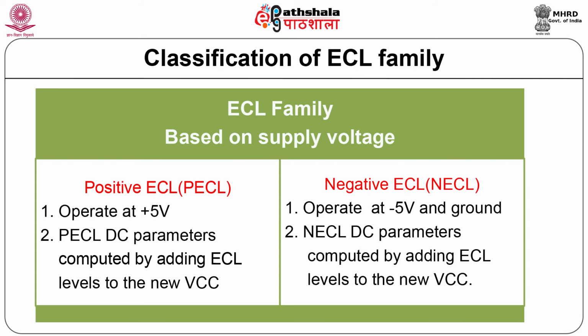We will also note that the voltage changes in ECL are small, largely governed by VBE of various conducting transistors. In fact, the magnitude of the currents flowing through various conducting transistors is of greater relevance to the operation of ECL circuits. They are also referred to as current mode logic or CML.